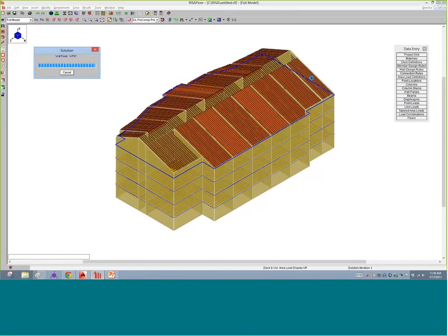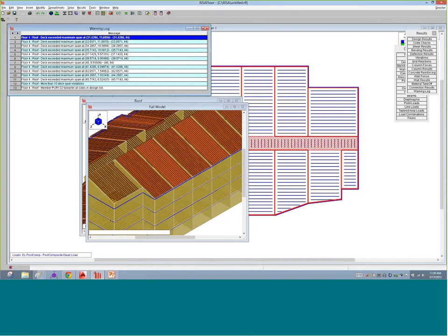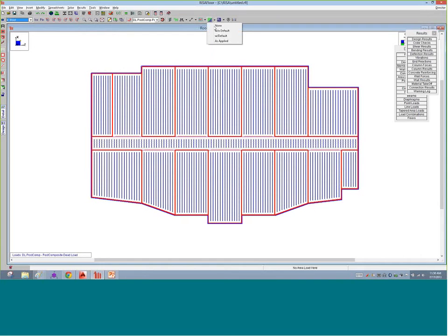So looks like I forgot these deck exceeds span. That's a nice warning to me that I did not address my span on the top of the structure. So we'll skip past that for right this second, and we'll take another look here. But what that was mentioning to us is that I forgot to address the direction of the deck on the top. I'm right now showing that I have the deck spanning in a direction which is opposing where I need it to be. It's going vertically, so it probably doesn't want to span that way. We want the loads to span horizontally so that these intermediate beams, all of my gravity beams, get loaded.